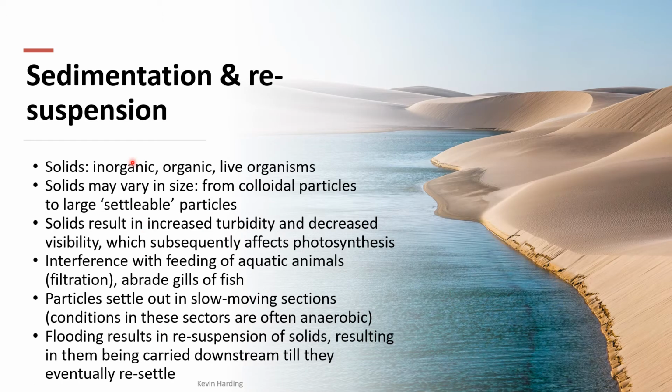If we have a little bit of a closer look at sedimentation and resuspension, sedimentation is going to involve solids. So it could be either inorganic, organic, or live organisms that are present in the water, and these are now polluting your water stream. Because the solids can vary in size, we have colloidal particles, which are small, to large, settleable, in inverted commas, particles. So theoretically, anything is settleable. It's just a matter of how long you are willing to wait for these particles to settle.